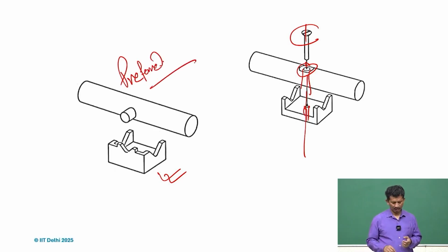So, knowing kinematic design principles or exact constraint design, we can design the contacts, design the mating, how the parts should be assembled and how they should communicate with each other. That is what I often say: the components, the parts, they also talk, and talking is the constraint.